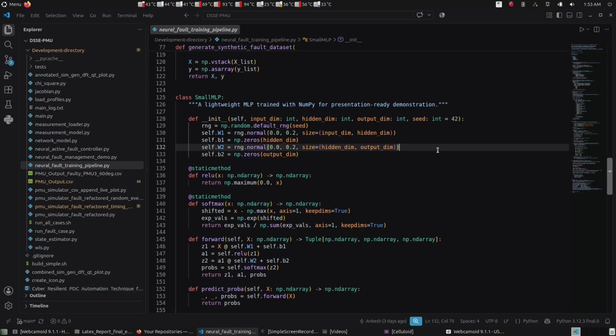So that was the entire idea, that we are using actual statistical techniques which calculate the weighted least squares and run a chi-square approximation algorithm to narrow down the fault. Then we make sure that the deduction that we have made from the statistical technique is correct. We added one more layer of neural inferencing that solidifies our output, whether the detection is correct or not. So now we have two layers that verify our final output in the device, which kind of fault we have encountered.